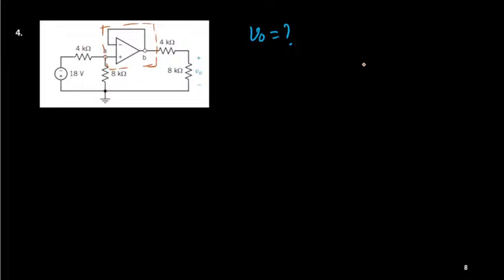This block, this is interesting, this is minus, this is plus, and you can see that this inverting terminal is directly connected to the output side. This is your output V naught, and input could be applied to this non-inverting terminal, that is your VI.